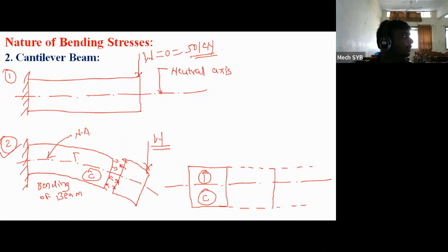And if you imagine the cantilever beam, assume it like your hand. If I apply a force on the upper side, how will my beam go? Downward. It will bend like that. After bending like this, what will this lower portion be under? It will be compressed. And the upper portion? Under tension. So it is also imaginable. That's why above the neutral axis the cantilever beam is under tension and below the neutral axis it is under compression. Now tell me the stress distribution diagram.